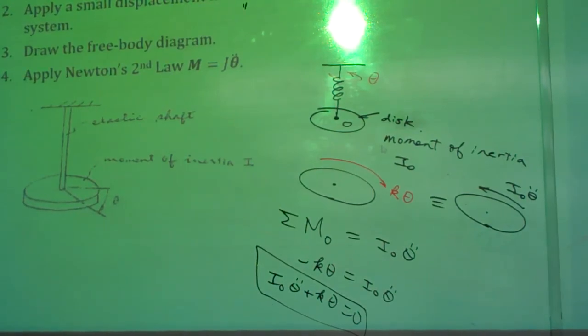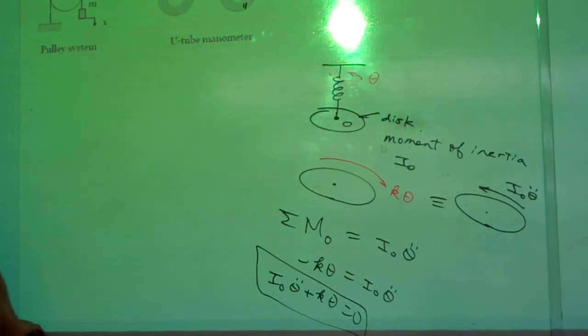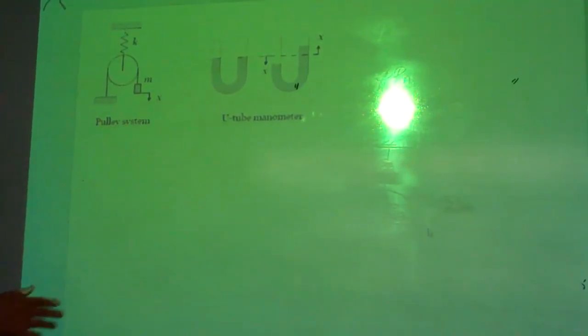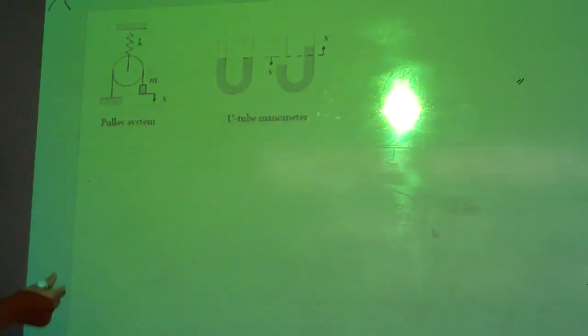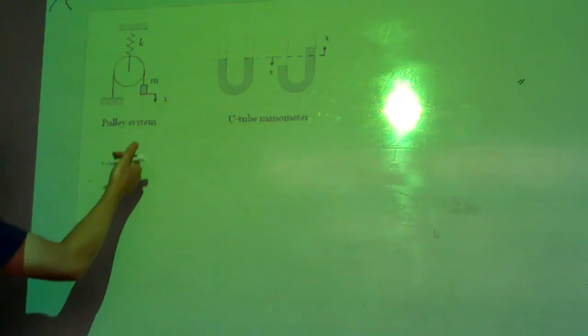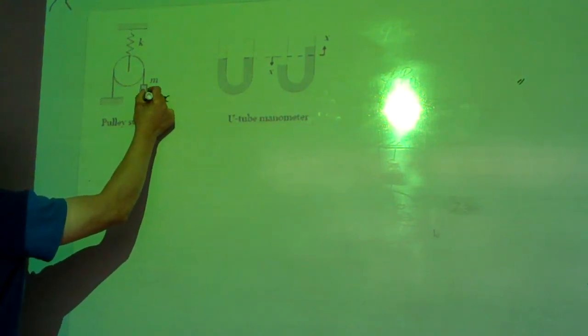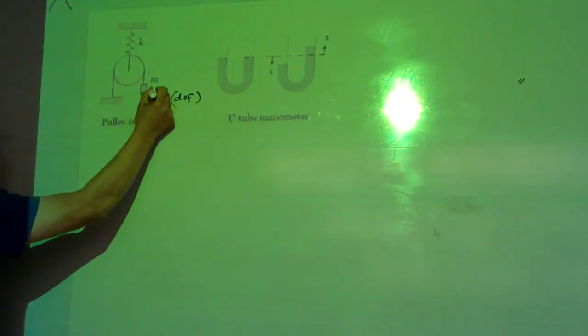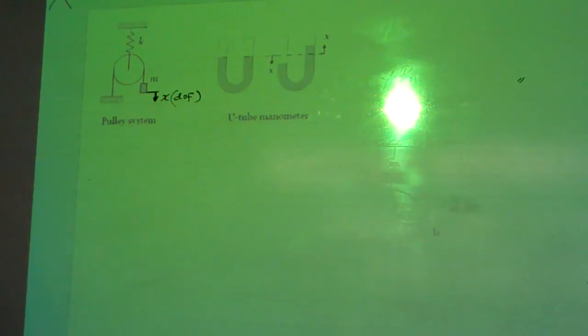Okay. Any questions? Okay, we can do a little bit of exercise here. So these are two examples. The first one is a pulley, and the example is to exercise how to formulate the equation of motion. For the first one, assuming say the pulley, this x is what we define as the degree of freedom of the vibration we pick, and we choose it to move downward.